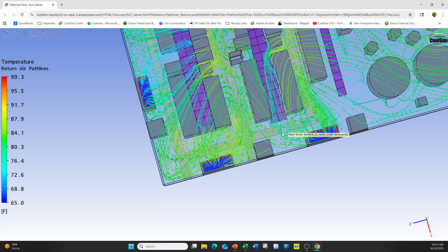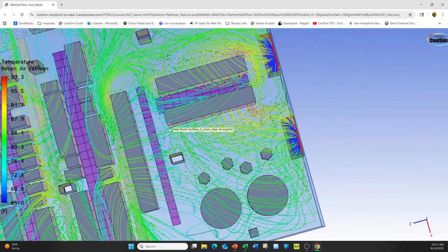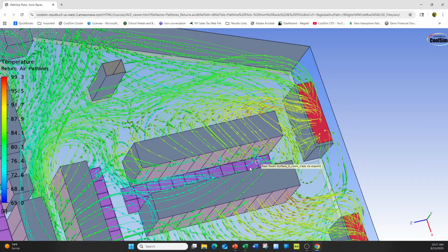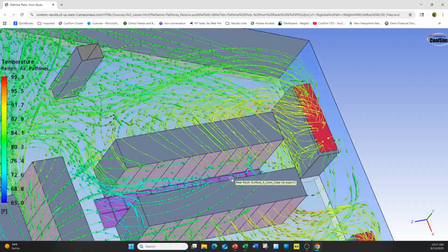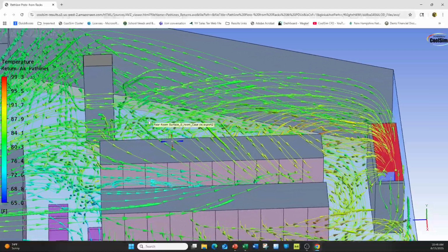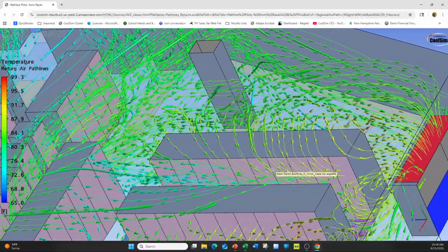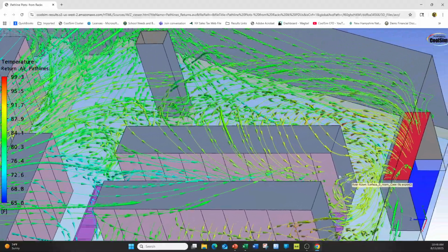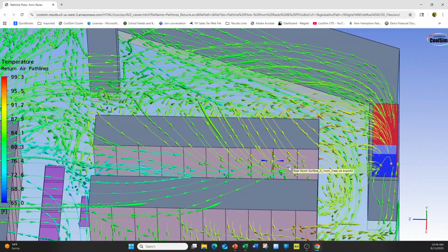There's one other area in this image where you can see a very similar thing. It's up here. Remember, these weren't performing very well, as I showed earlier, and therefore you can see the air coming right up over the top of those racks and being inhaled back into its own intake, causing the performance of these racks in this region of the room to be poor.